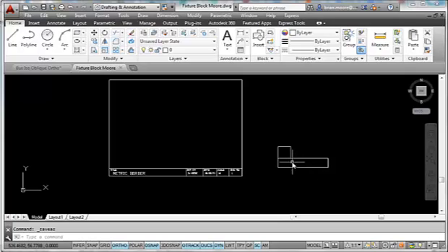So that's where we begin usually, is creating one of the views, the front view, and what we do is we consider the front view to be the side that would best describe the shape and size of the object. And this would be the best one for this object. So now I need to start drawing the top view.